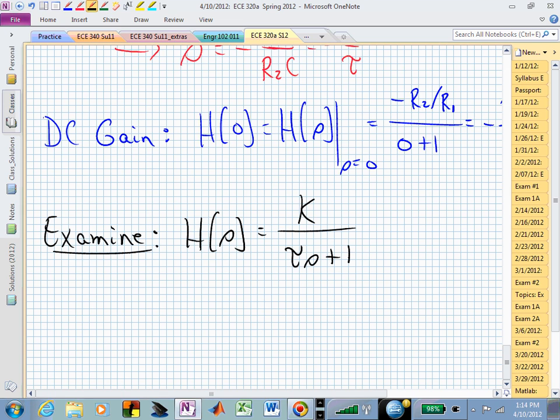But now you know where those come from. If somebody said, build me a low pass filter after today's lecture, you can do that. Very easily. Go see Josie, get an op amp, a resistor, and a capacitor, a couple resistors, and you're good to go. You just need to know what the bandwidth is to pick those R's and C's.